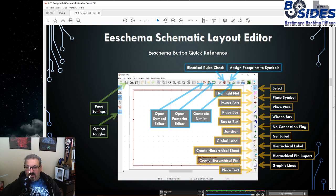We have a button that will allow us to check electrical rules to make sure that we didn't leave anything unconnected, or we didn't create a short or something like that in the circuit. And then we also have a button that lets us assign footprints to symbols. And then on the right side here, this long list of tools, these are all tools that we're going to use when working with the schematic.